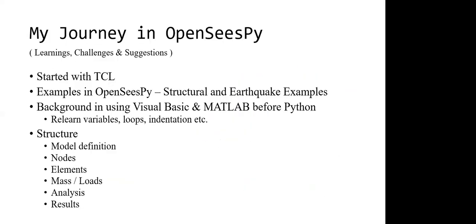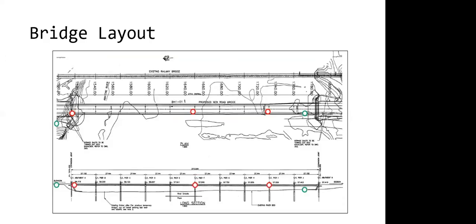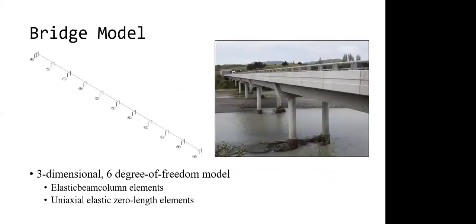If not, I can ask some questions related to modeling. Can you go to the start of the presentation? I want to highlight some points that I think are useful for everyone to keep an eye on. Some are questions, some are points to highlight. You said you're using elastic elements, and when modeling the damage, you're using reduced I values in the top 1 or 1.5 meters, right? How did you come up with that 1 or 1.5 meter value?